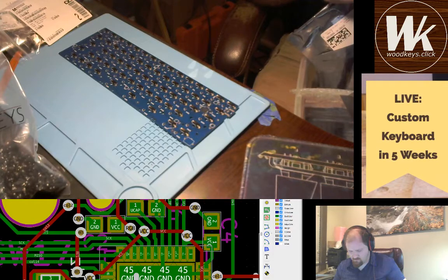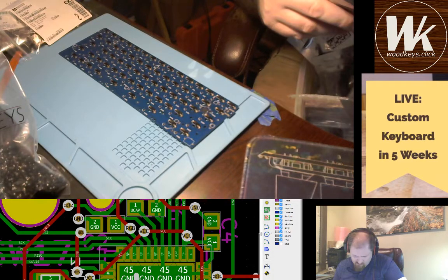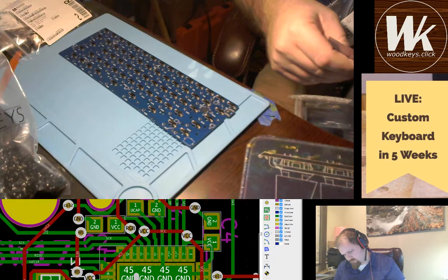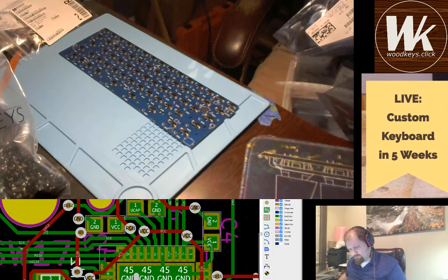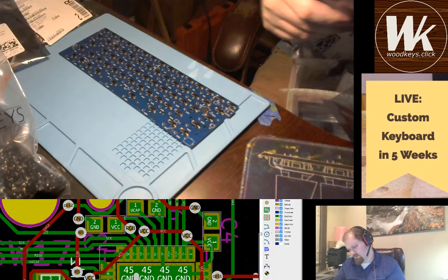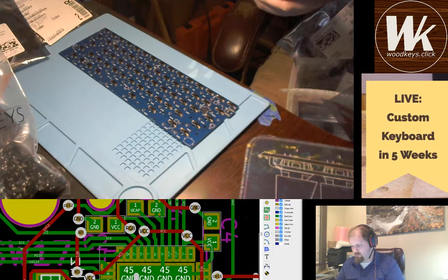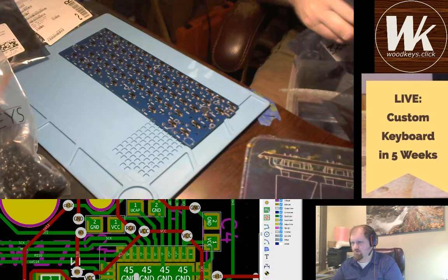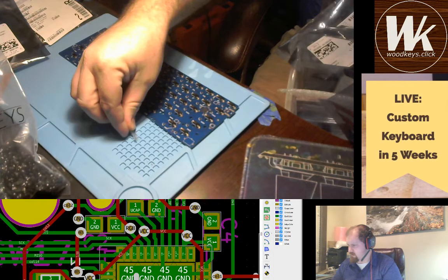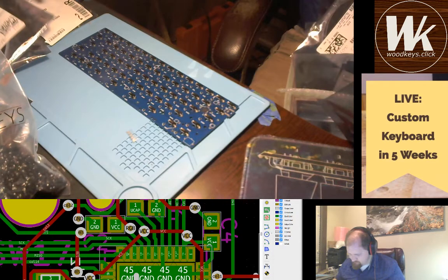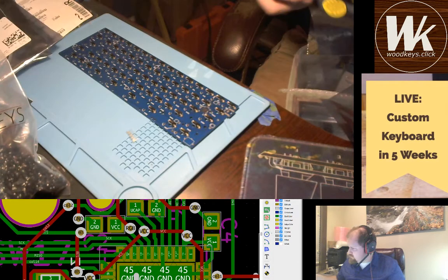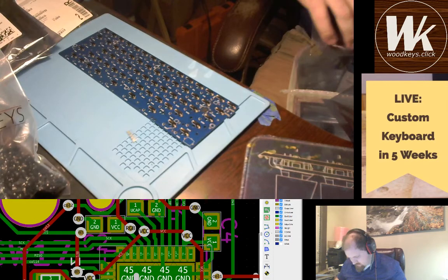Those are really tiny. I have a bunch of 0402 parts in here from some previous builds that are just really not fun to work with. Alright, there's 1/10 of a microfarad. There is a resonator I'm going to need here in a minute. 1 microfarad. 22 ohm for the USB termination resistors. And I think that's all I need.